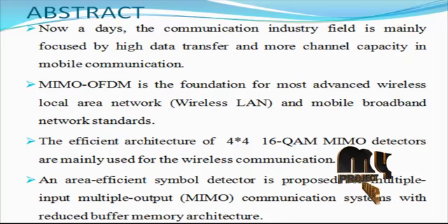Therefore, the implementation of a low complexity MIMO detector is needed, and it is a main challenge in the SC-FDMA framework. Several designs have been proposed for SC-FDMA MIMO detectors, among which the linear frequency domain equalizer FDE receivers, including minimum mean square error and zero forcing, are often used. Successive interference cancellation and iterative techniques can be used to enhance the performance of FDE receivers.